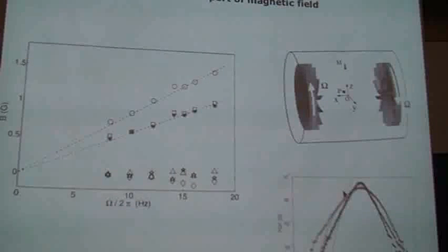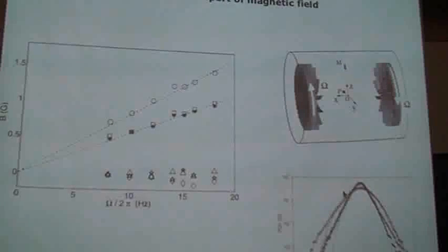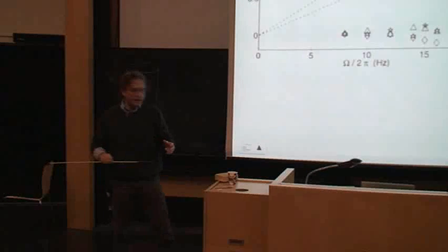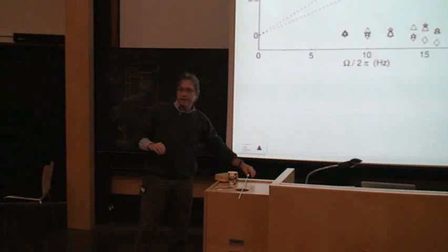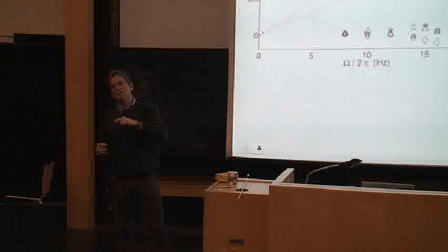Now, in kinetic gas theories, you only need one process, the collisions, to give you most of the transport coefficients. So the Prandtl numbers are 1, basically. It's the same origin for all these transport coefficients, and you get a value of viscosity, for instance, with the same mechanism, so the Prandtl number we guess is of the order of 1.